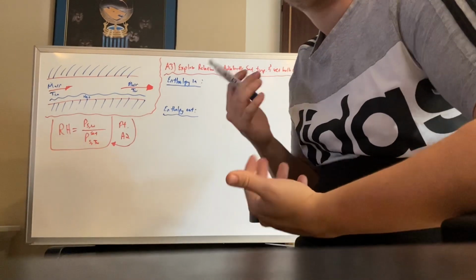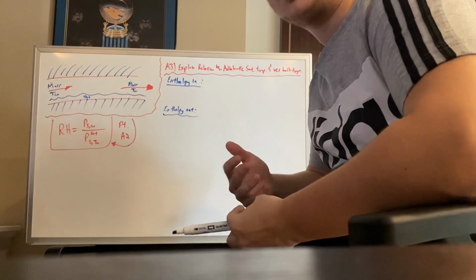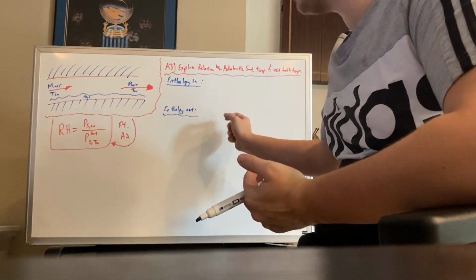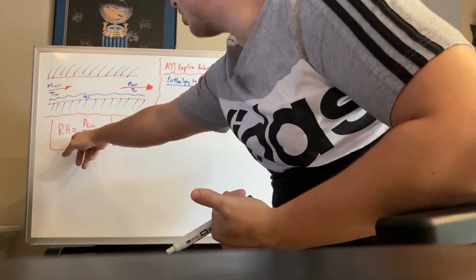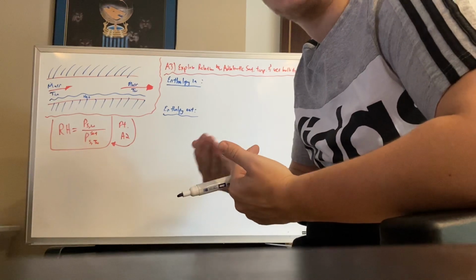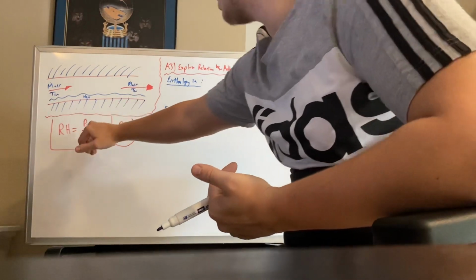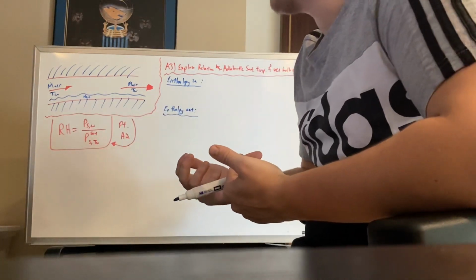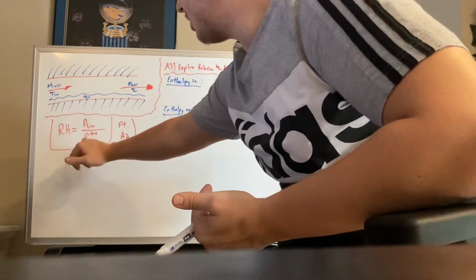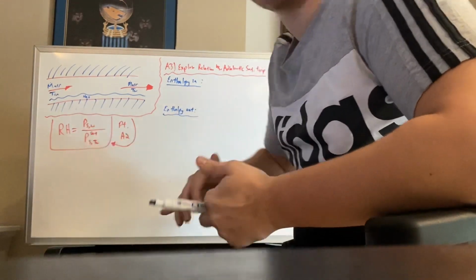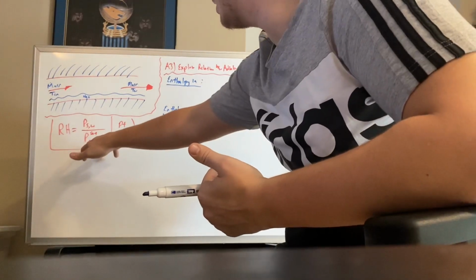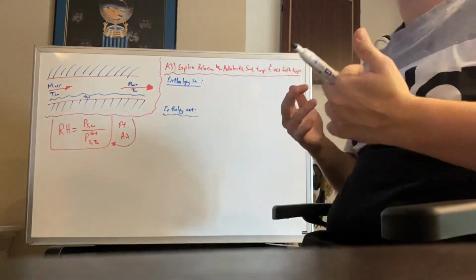Lewis relationship. Heat transfer coefficient over the mass transfer coefficient is equal to the density times the heat capacity, which we'll also be using in this part of the exam, as well as in part 2 where we found the relative humidity between the wet and dry bulb temperatures. It is designated by the partial pressure of water at the surface or far away, depending on which way you want to look at it, divided by the partial pressure of the saturation temperature, which is the vapor pressure at whatever temperature it is at the same location, whether it be the surface or far away from it.